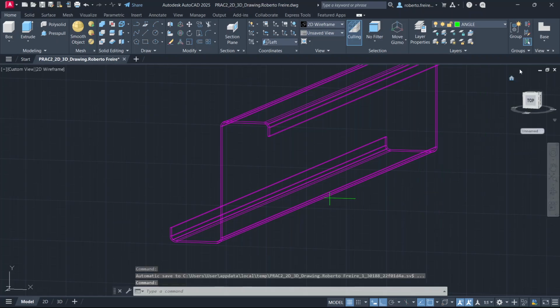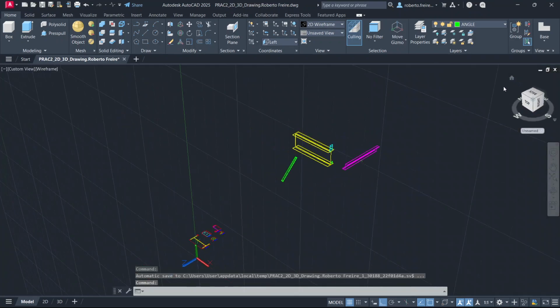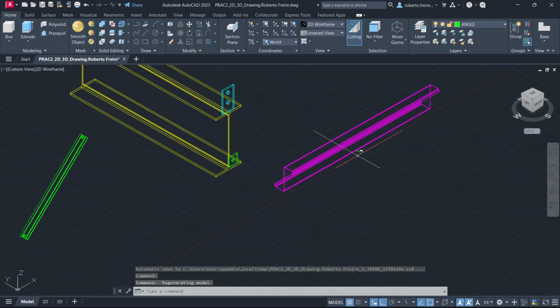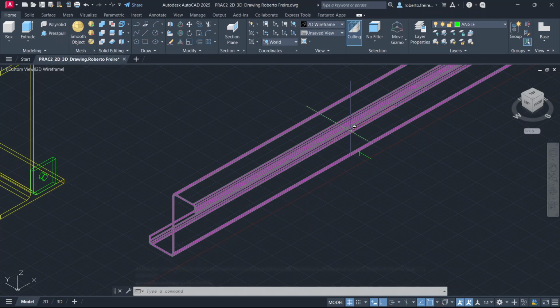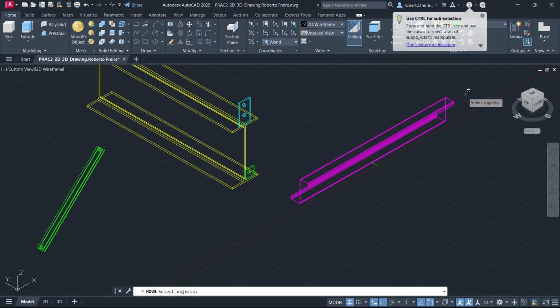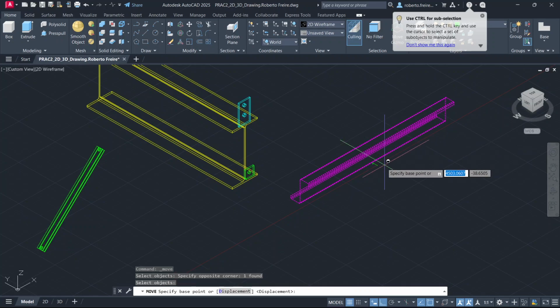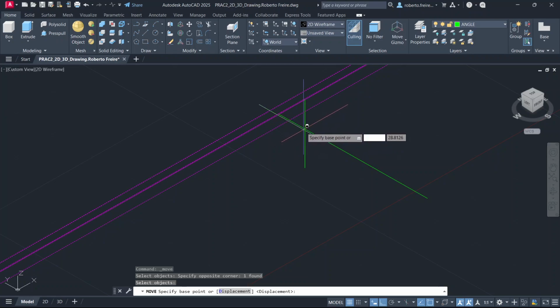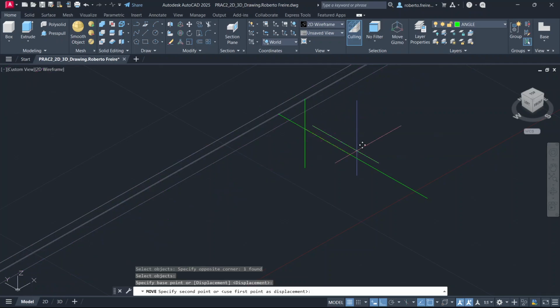rafter. Let me click on the house button and click on the world, and now I'm able to position this purlin on top of the rafter behind this cleat. How can I do this one? Command move. I'm gonna select my purlin, press enter, and I'm going down. Actually, I'm going close to this intersection. Click there, zoom out,